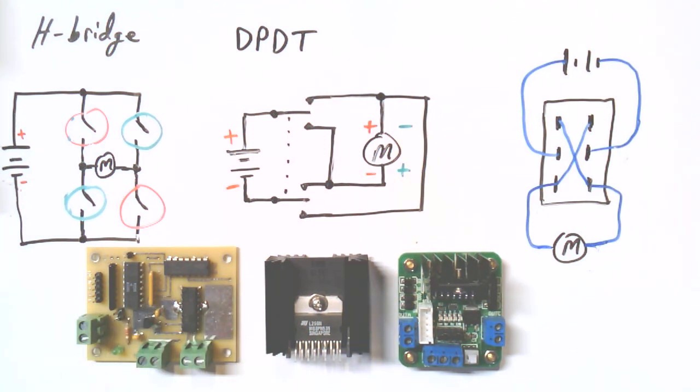Some of the surrounding chips then add what I was saying about the digital logic, just so that you can control with a minimum amount of bits, and you can also make it impossible for, like, these two transistors to be on at the same time, for example. So there's some built-in simple gate logic that is important to protect from bad things happening. So we'll look at that.